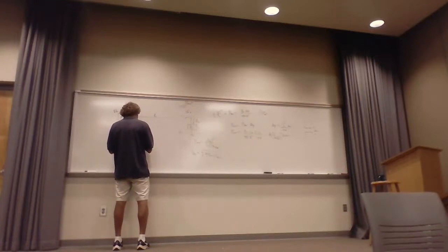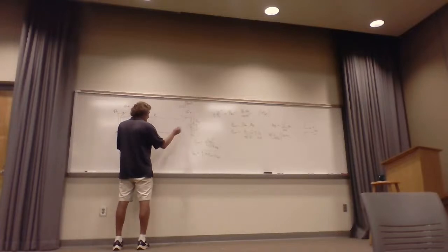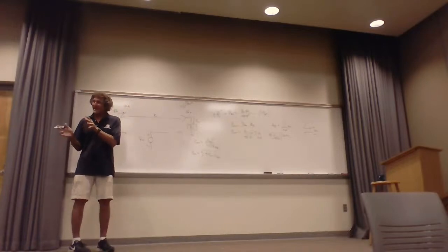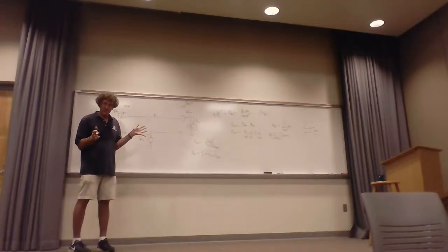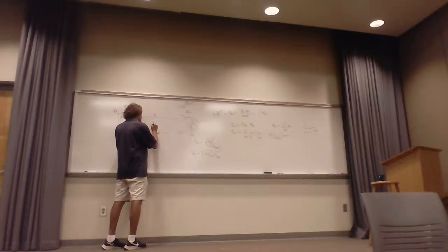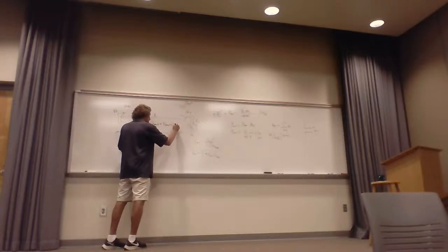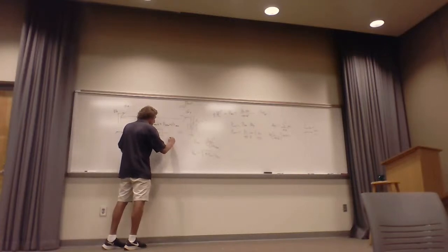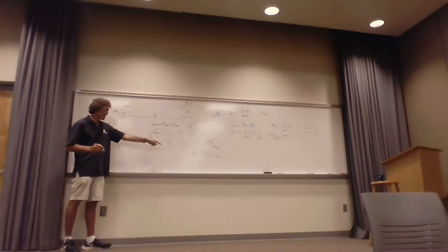Now, when you have the open circuit, you use that voltage, plus and minus V OC, which is there, and now you put the load on. But I've got to tell you this: remember that antenna impedance is still there. You all with me on this? So you still need to put the actual Z antenna here, and Z antenna is equal to R rad, the radiation resistance, plus jX antenna. So you've got Z antenna, then you put ZL. And then to calculate this current I, you would take this divided by the sum of the two.